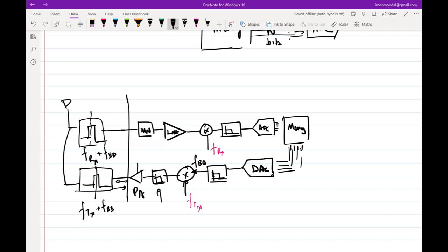There will be a transmission line, but we know that to some extent that is 50 ohm. But I don't know what is at the other end of the transmission line. So typically that's why PA design becomes much more critical. The good thing about the PA is that you do not have to bother about blockers because the PA itself is such a high power device. So you say that, okay, there will be reflection that comes back to the PA, as long as whatever is reflected and coming back to the output of the PA is not large enough, we are good. So that's the trade-off.